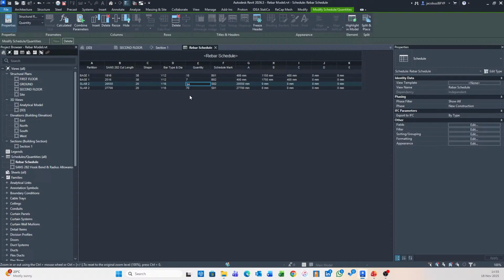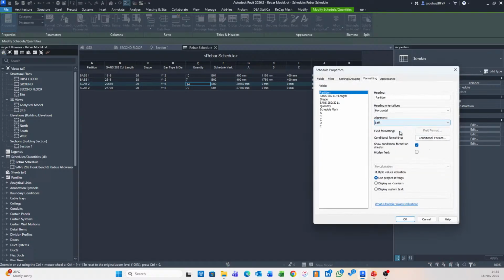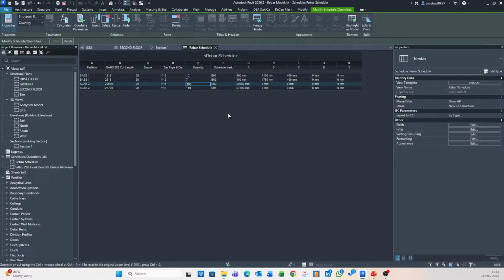All right, so that is something that you really have to watch out for, and why I recommend approaching it slowly but surely. Okay, so this quantity, you do want to set its calculation to calculating totals, because this is now displaying the quantity basically per set. Okay, so we can check that out.